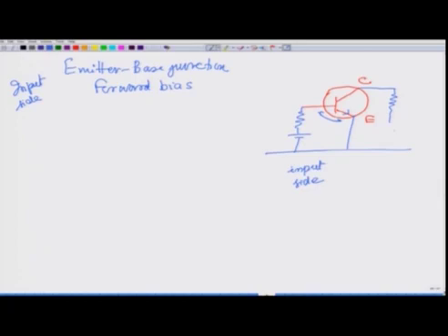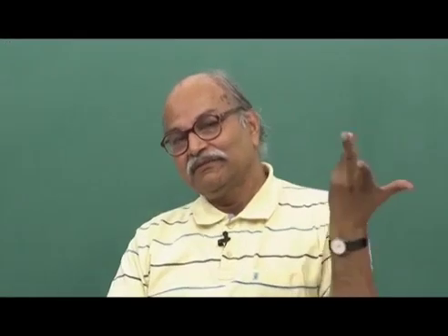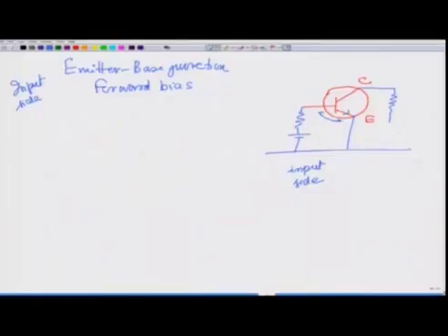In this basic transistor circuit which is used for amplification and some other applications, normally this junction is reversed biased, but sometimes it gets forward biased also, but normally reversed. So, let me try to make it reverse bias. So, how do I put the battery here? The other end of the battery will of course be connected here. We have only these three contacts. We have contact at this emitter, we have contact at this base here, and we have contact here at C, collector, and the emitter is common in fact on the two sides, input side and output side.